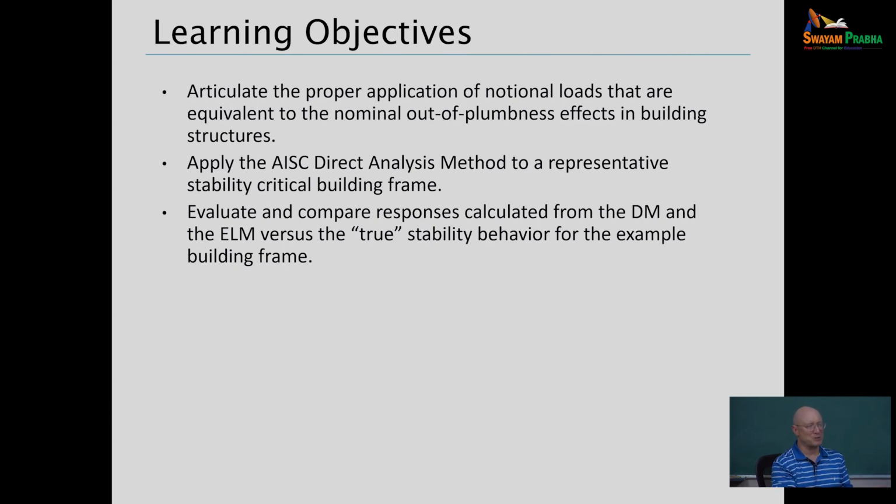Now, my best understanding of the Indian standard is that it is very close to AISC's effective length method when it comes to handling everything. You're getting a buckling result, or K-factors that feed into calculating a buckling result, and then you get buckling loads that feed into your member strength formulas for axial and for bending.